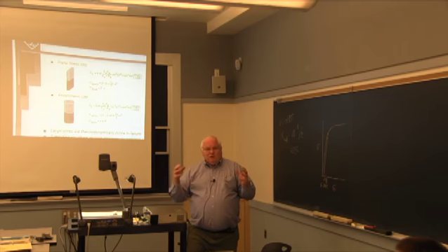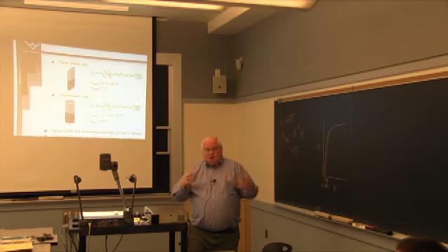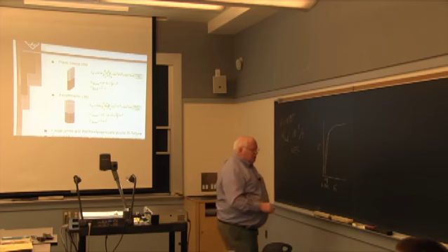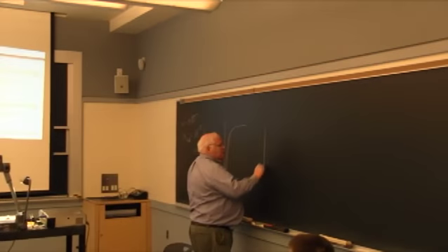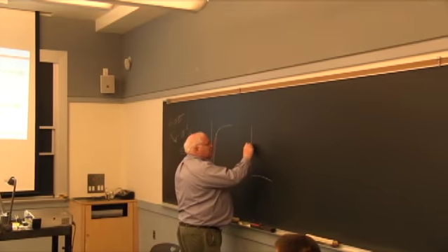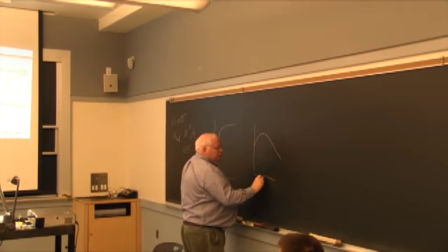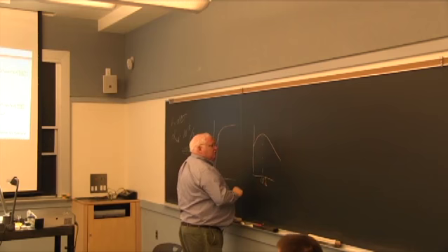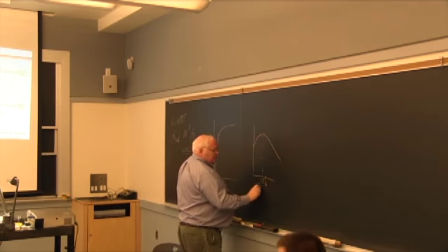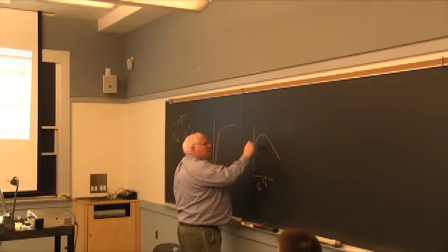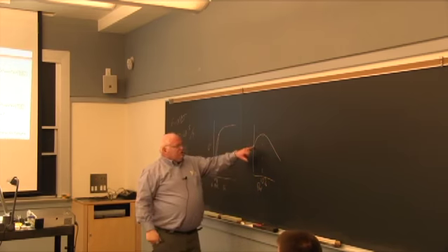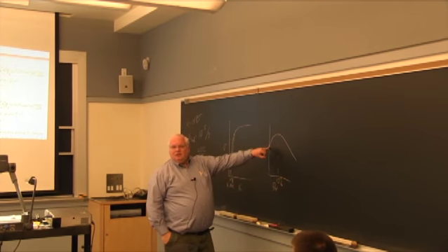Voids are wonderful, and I mentioned that I actually had a student do a doctoral thesis 10 years ago, and she showed through modeling and some experiments that if you looked at the amount of porosity at an interface in a ceramic-metal joint, you actually would get something like this, where 10% porosity gave you the strongest joint. So this is porosity and this is strength. Actually, you had the residual stresses would kill you here because of the thermal mismatch.